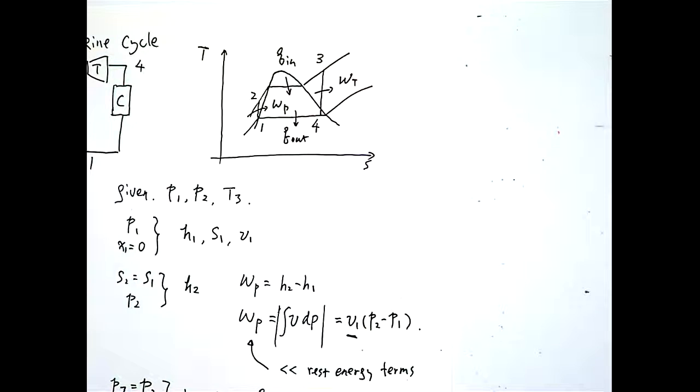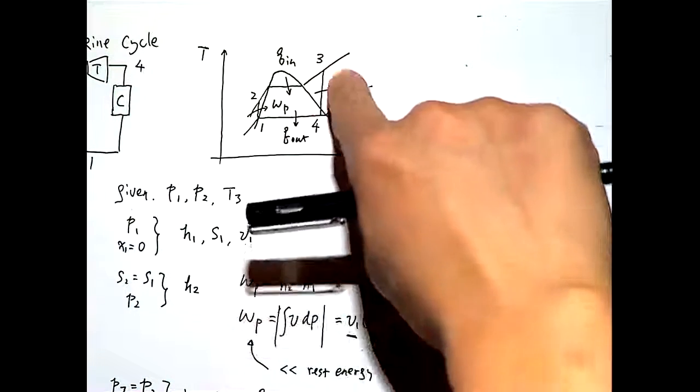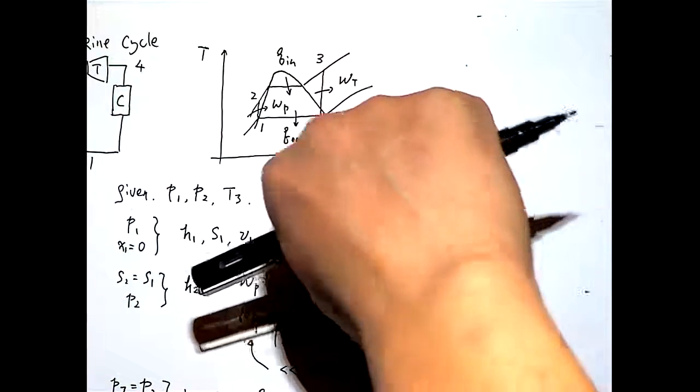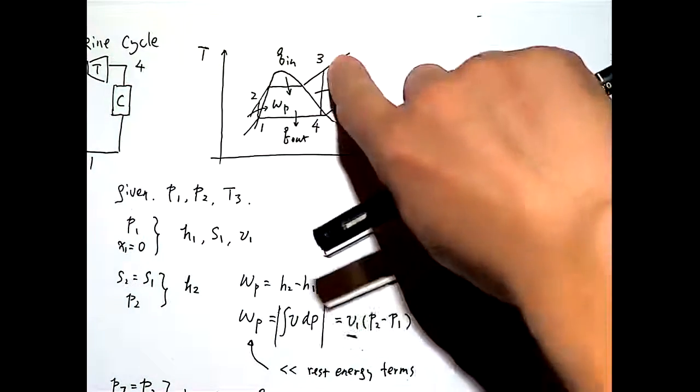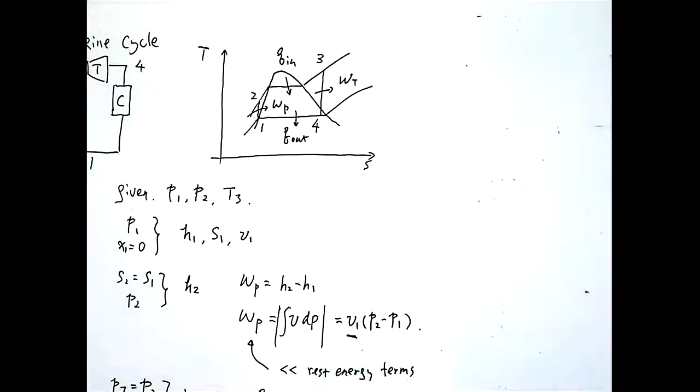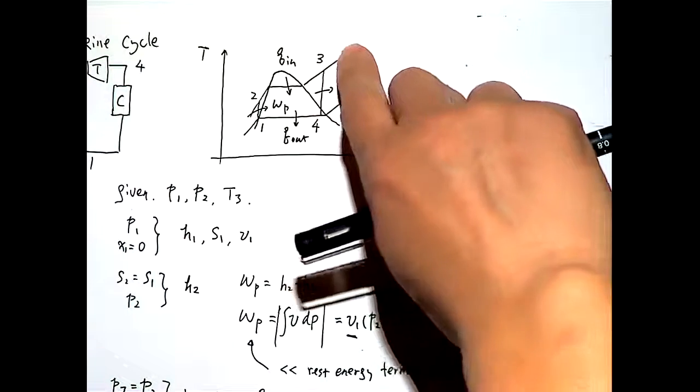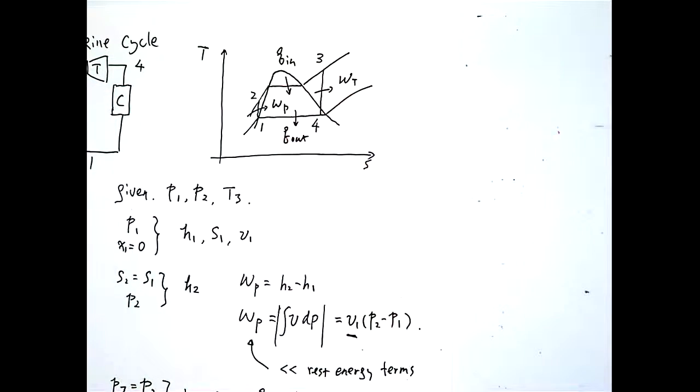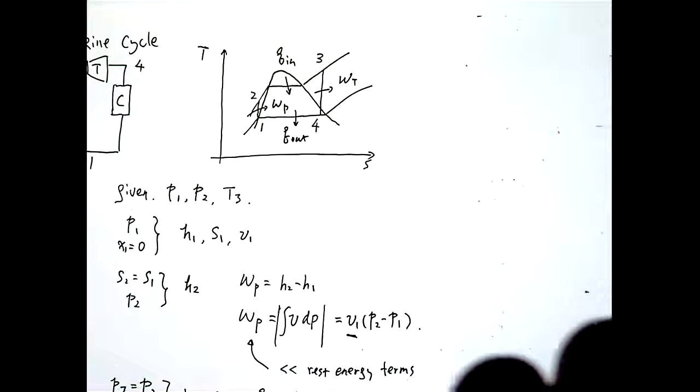So in that case, if you end up with that situation, in general, that's not the case. When a steam turbine is running, in general, it ends up within the saturation dome. But if your calculation shows the problem, in reality, it's possible. It ends up outside this saturation dome. In that case, you need to go to a different property table to find all these properties.